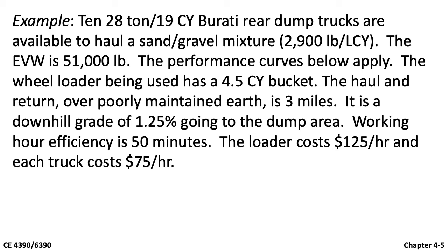The performance curves below apply for this machine, and the wheel loader being used has a 4.5 cubic yard bucket. The haul and return is over poorly maintained earth, with a distance of 3 miles, and a downhill grade of 1.25% going to the dumping area.